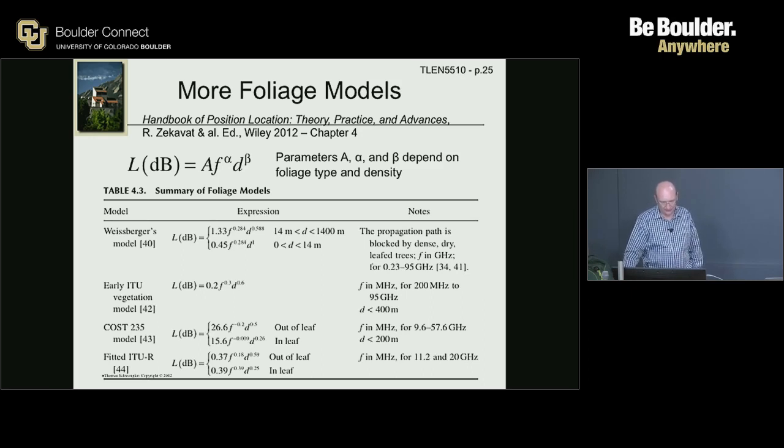And so some of those models try to calculate the path loss exponent through the forest. But instead of a certain loss per meter of forest, it turns out it's usually more of a loss per square root of the distance in the forest, right?